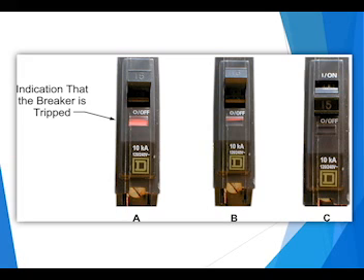The time limit breaker is a code term that we use for Table 29 when we start talking about sizing different types of breakers. This type of breaker not only protects against short circuit conditions, but it will also protect against any overload conditions. And it uses a bimetal strip for time delay tripping, and it uses an electromagnetic trip element for instantaneous reaction.